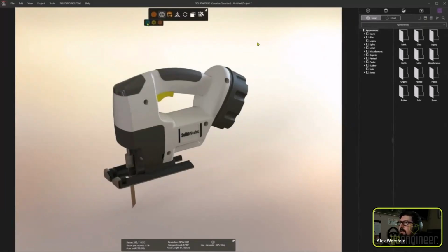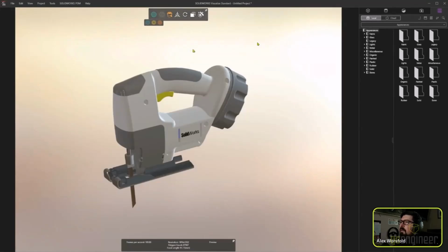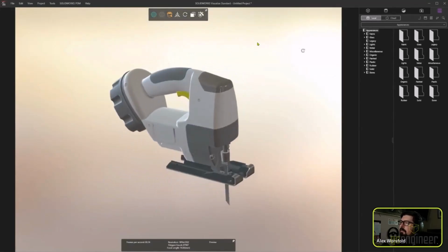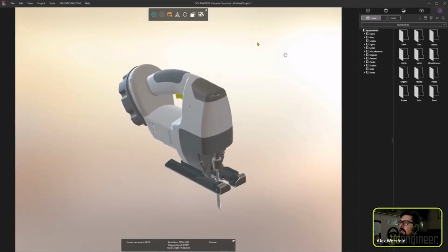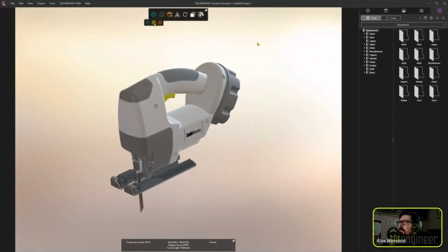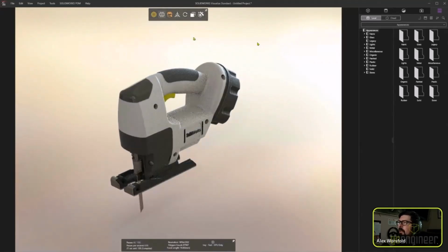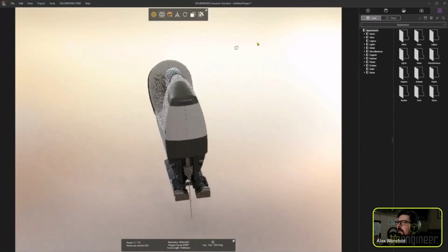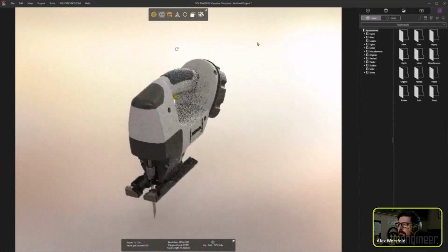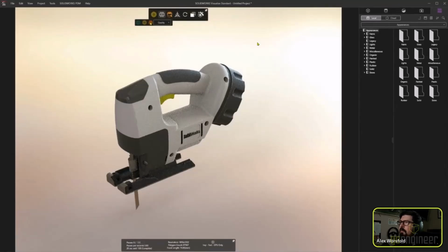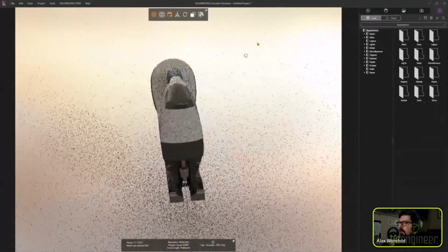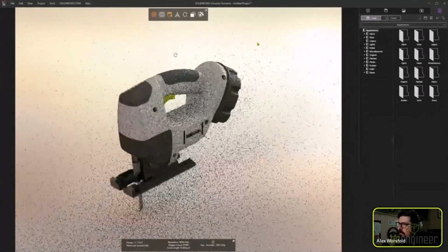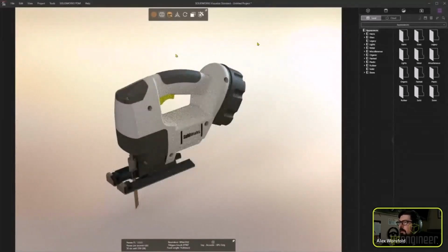In the graphics area here, you have different preview modes. So that green button there, that's your normal view that you would see inside of SOLIDWORKS. This is not rendering at all. The yellow button is only available to NVIDIA cards. This is ray tracing. So if your card supports it, you'll see that option. And then the orange button is full-on path tracing. So this is what normal rendering inside of SOLIDWORKS, PhotoView, PhotoWorks has done for many years.